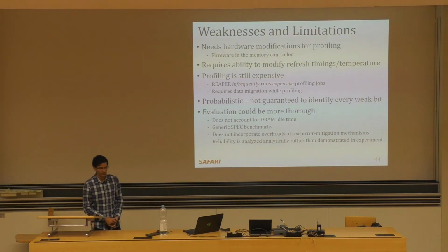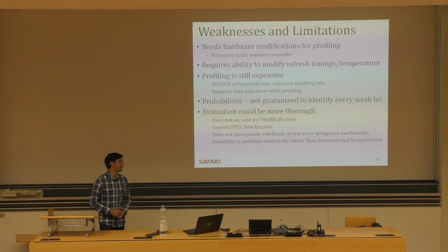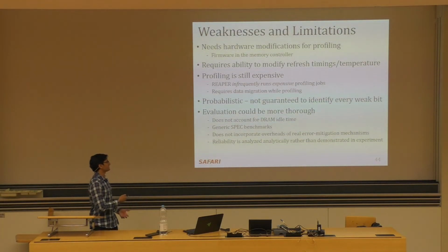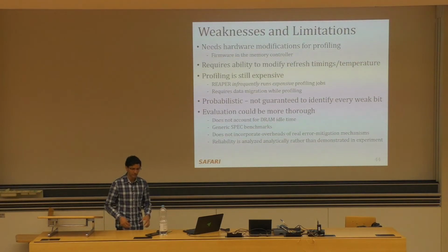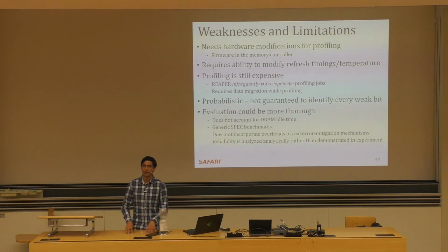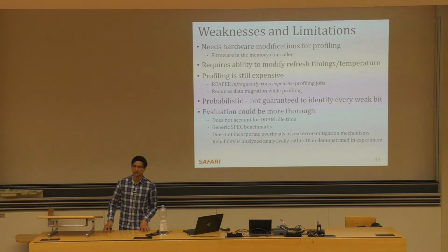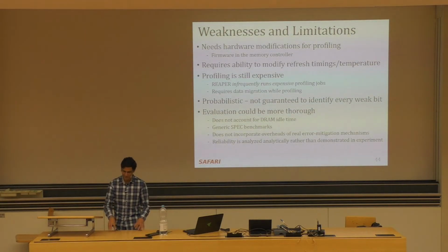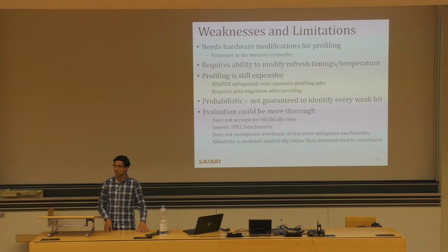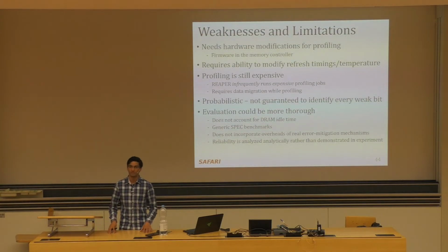And finally, as always, we can complain about the evaluation, right? So I think the evaluation here has several limitations. The first is that it does not account for DRAM idle time. And this is important because the characteristics of how the DRAM error patterns will look during idle will actually be quite different from during normal operation. Right? Because during normal operation, you're accessing the device, changing the data patterns, introducing a lot of circuit level noise to the device, which will cause the retention times to change much more dramatically than if the device is just sitting there idle, right?